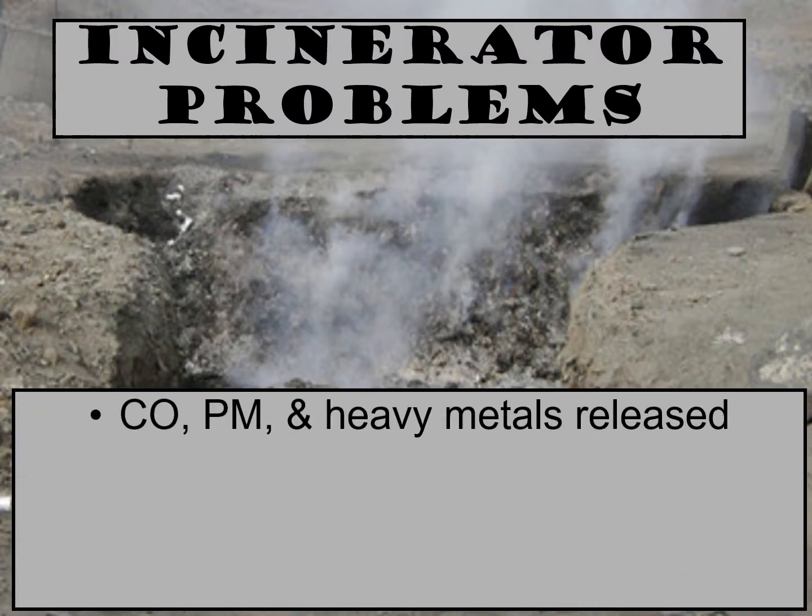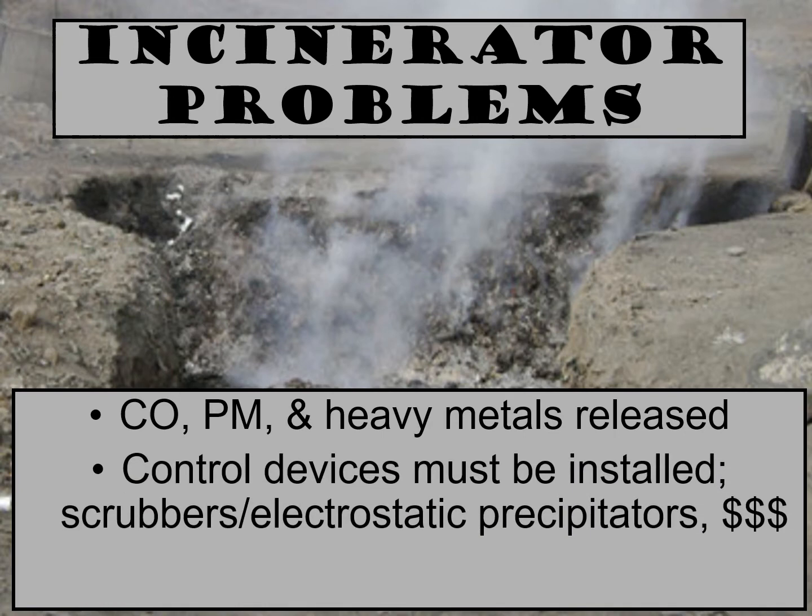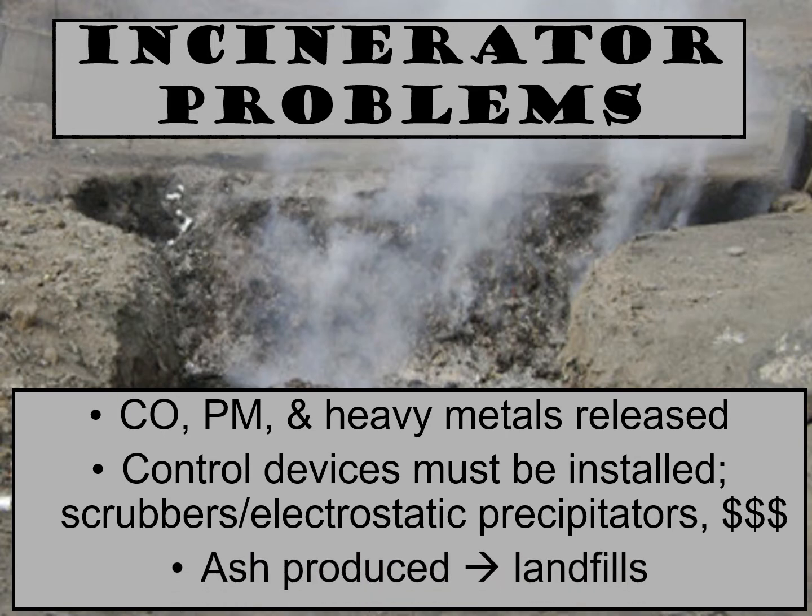As you can imagine, there are issues with incineration, and the biggest one is air pollution. So carbon monoxide, particulate matter, and heavy metals are all released when you burn solid waste. So that means at these facilities, they need to use air pollution control devices to capture those air pollutants. So wet scrubbers and things can be placed on these smokestacks, but as you know, those can be expensive. And lastly, ash is produced. Just because you burn the solid waste doesn't mean there's not going to be any left over. So all that ash that's being produced will eventually make it into a sanitary landfill.